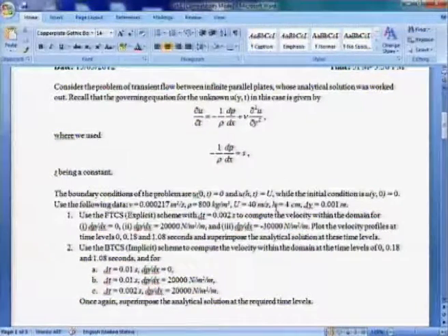You have been asked to look at the explicit method with a delta t of 0.002 seconds to compute the velocity profile for 3 different cases: no imposed axial pressure gradient, then an adverse pressure gradient, and later a favorable pressure gradient.